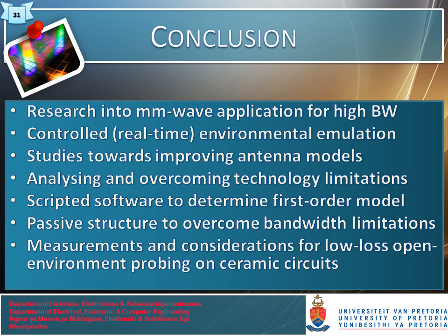Scripted software is presented to determine first-order equivalent circuit component values that decrease the complexity and computational time of solving transfer functions that can become complex and possibly impractical. Passive structures as components in the circuits are prioritized to maximize bandwidth capability, where the GBP, or the gain bandwidth product, of active devices incurs limitations within the chosen technology node.